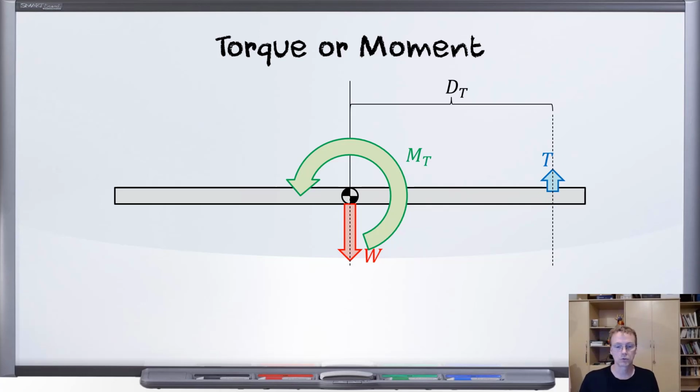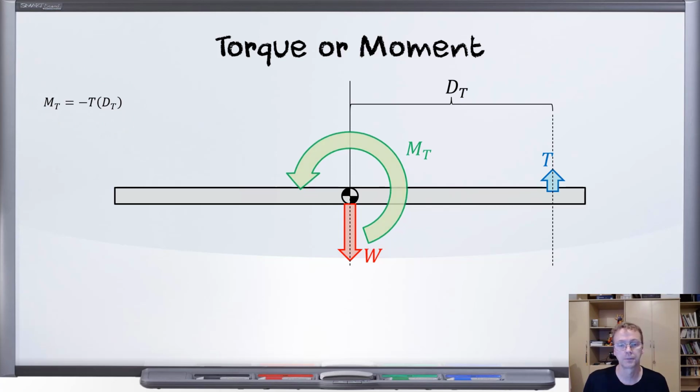And also, I ditched the plane, but the plane's nose was over here on this side. So this is a nose down torque. By aircraft convention, the pitching moment is considered positive nose up. So this is a nose down torque, and therefore we're going to put a minus sign to indicate nose down. This is not nose up. This is the opposite of nose up. It's nose down. So there's the torque or moment from the tail.